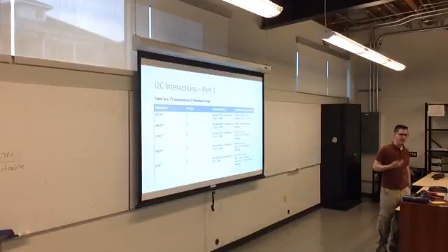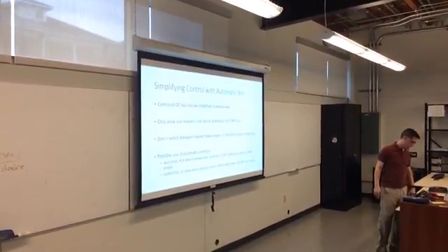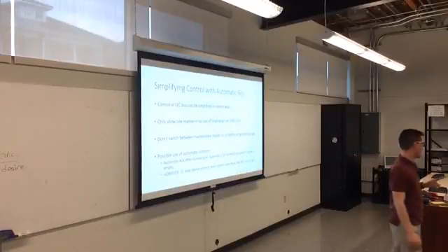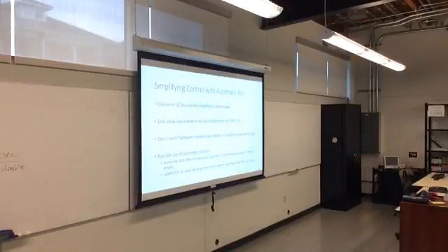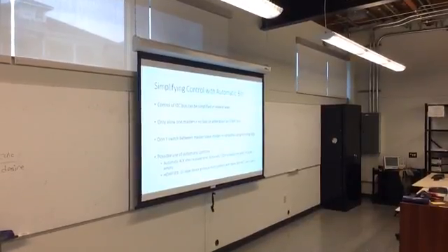There are two ways to simplify it. The first way is to be the only master on there and not do a multi-master system. In a multi-master system, masters can talk to other masters, which means that some devices become a slave device on demand, and that state machine gets even more complicated. So you don't need that. If you only have one master, then you never lose arbitration. So that whole bottom half of the chart, gone.